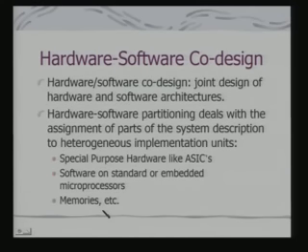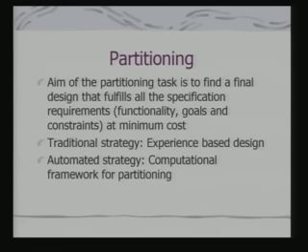So, the key issue for an embedded system design is this hardware software co-design, which implies hardware software partitioning. The basic aim of partitioning tasks is to find a final design that fulfills all the specification requirements, functionality, goals and constraints at minimum cost. You can understand why this partitioning requirement will come in.